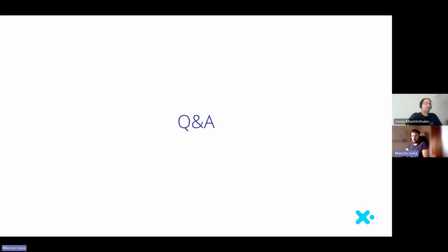What about the common mode chokes on the input side of the DC-DC converter? It's the same. I mentioned the output side, but on the input side it works similarly. Maybe what we can do is add a way to indicate where the common mode choke is placed, on the output or on the input. The only thing that changes is that to calculate the current, you take the input voltage and the output voltage, or the output power.